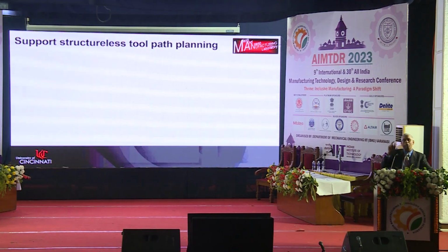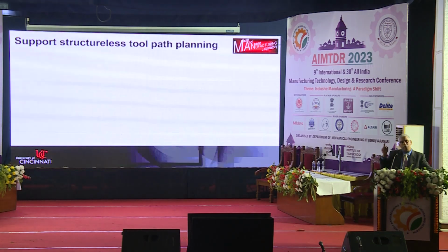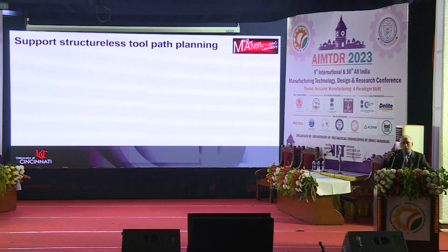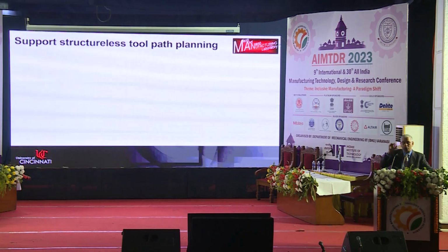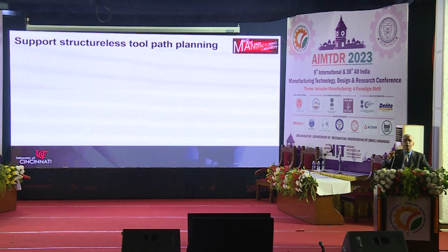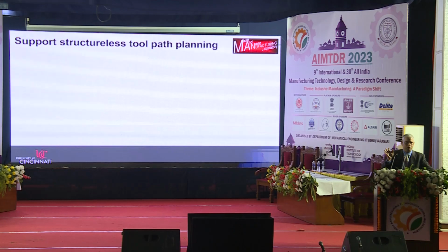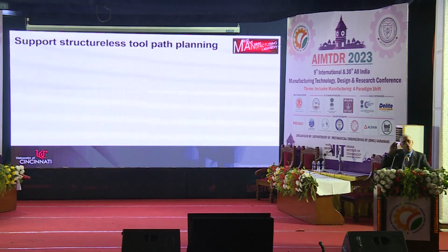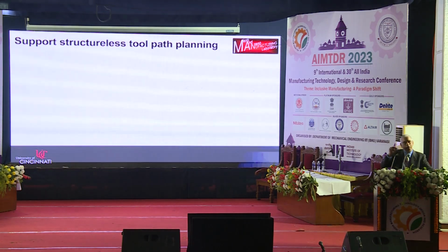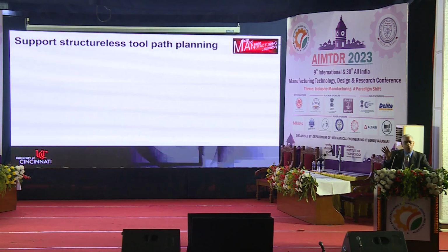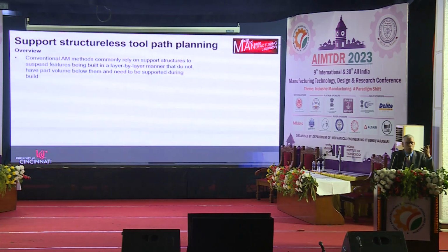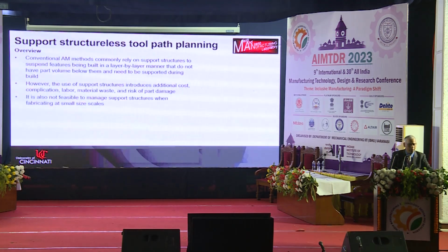Second thing is, particularly if you are going to move this additive manufacturing from macro level to micro level or even nano level, at macro level removing the support structure is difficult, at nano level it is impossible. So you have to come up with a way so that you do proper toolpath planning, so you don't need any support structure at all. So that is the motivation of this particular study.